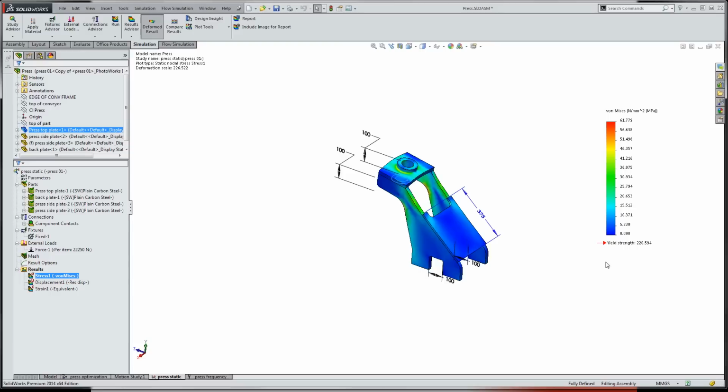Well, you can see there is nothing permanently damaged in our actual design because the maximum stress is less than the yield strength, and displacements are showing us 0.32 millimeter maximum displacement. Well, the original design is simply confirmed with the set of conditions or constraints that we have defined.